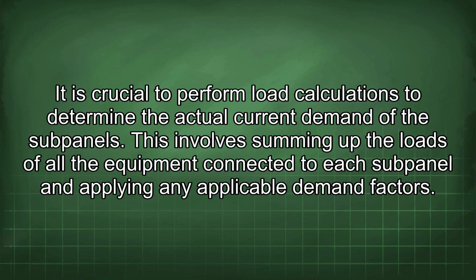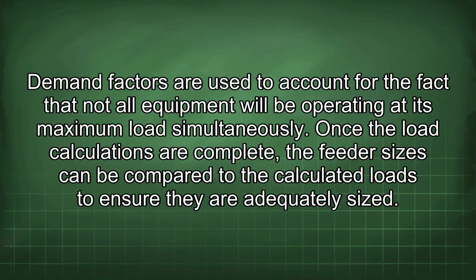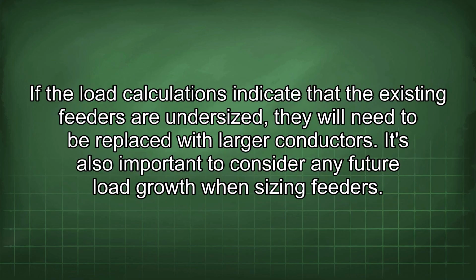This involves summing up the loads of all the equipment connected to each subpanel and applying any applicable demand factors. Demand factors are used to account for the fact that not all equipment will be operating at its maximum load simultaneously. Once the load calculations are complete, the feeder sizes can be compared to the calculated loads to ensure they are adequately sized. If the load calculations indicate that the existing feeders are undersized, they will need to be replaced